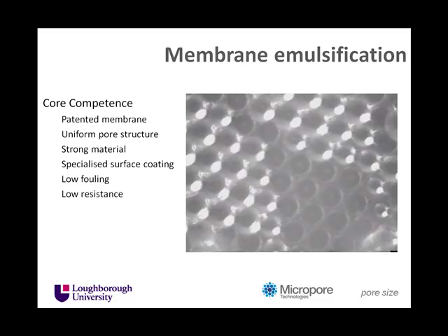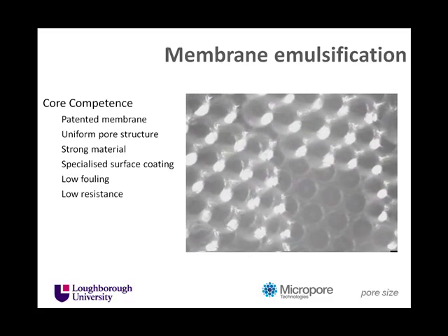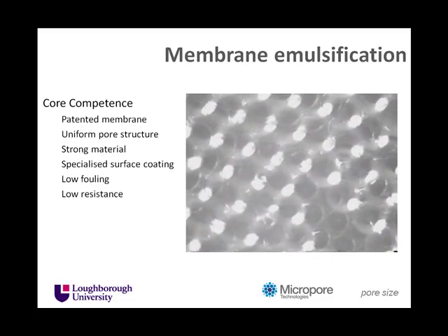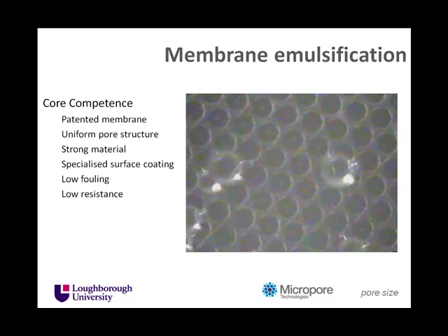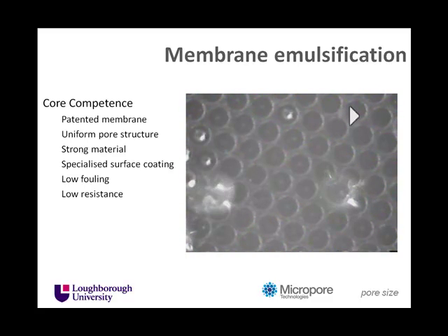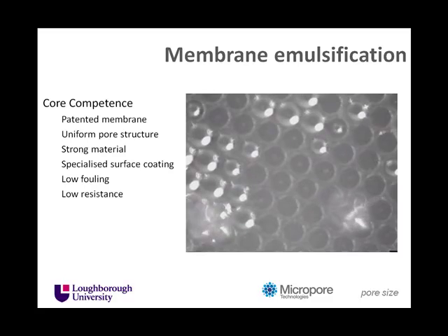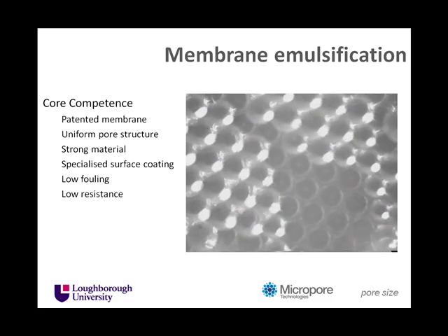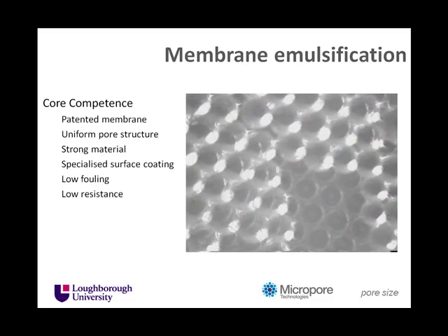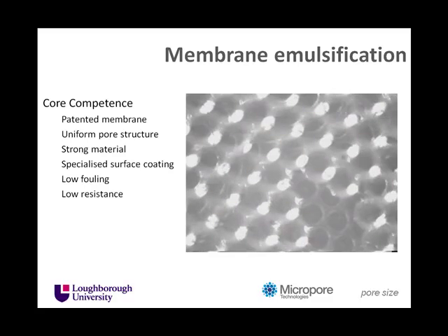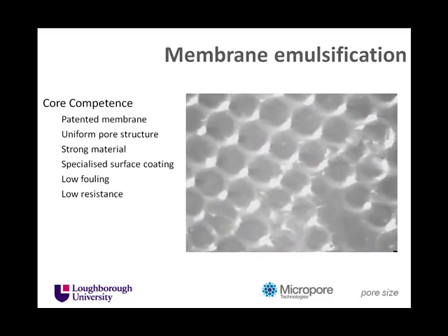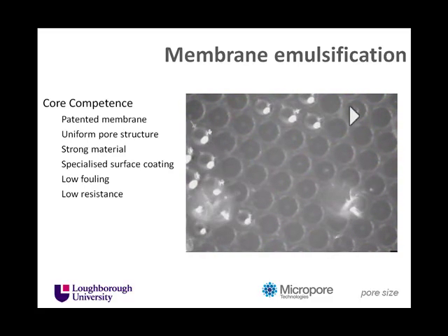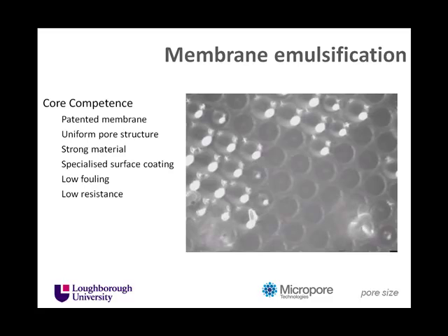This is the process of membrane emulsification. We have an oil phase here that's being injected into an aqueous phase. It's being pushed through those little pinprick holes in the middle of the exterior hull, and as the membrane is all very uniform in size, you can clearly see that it's producing some very uniform droplets of oil dispersed in water. And if those oils are a monomer, then it's possible to polymerize those droplets to form a polymer, to form a solid surface, to form a solid particle.